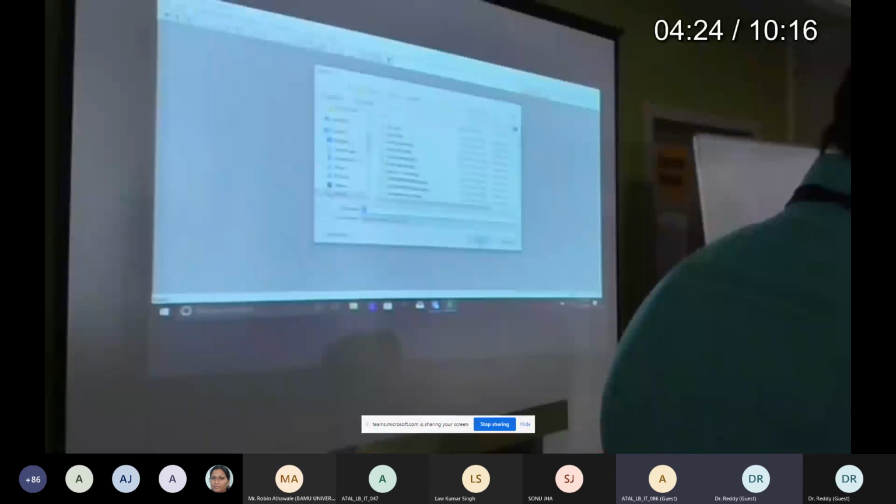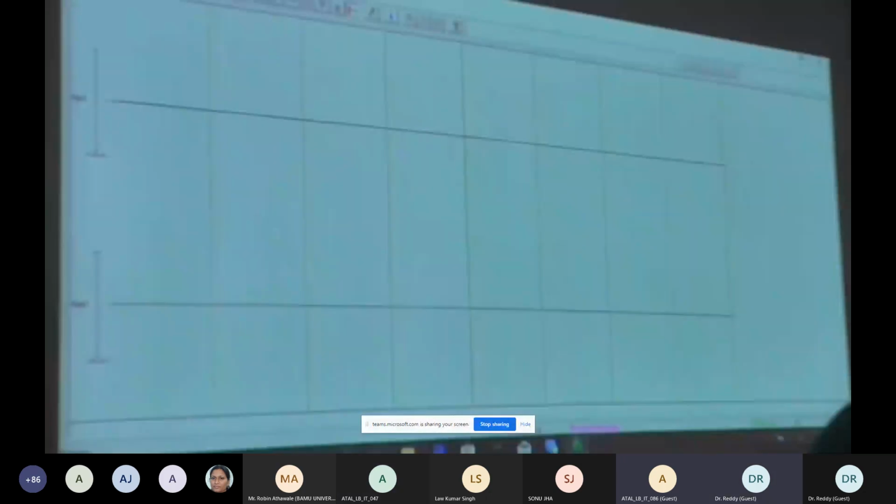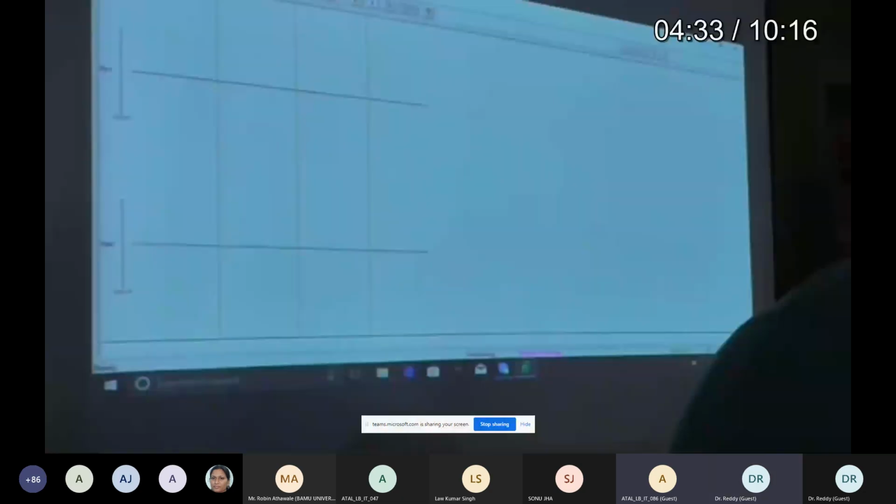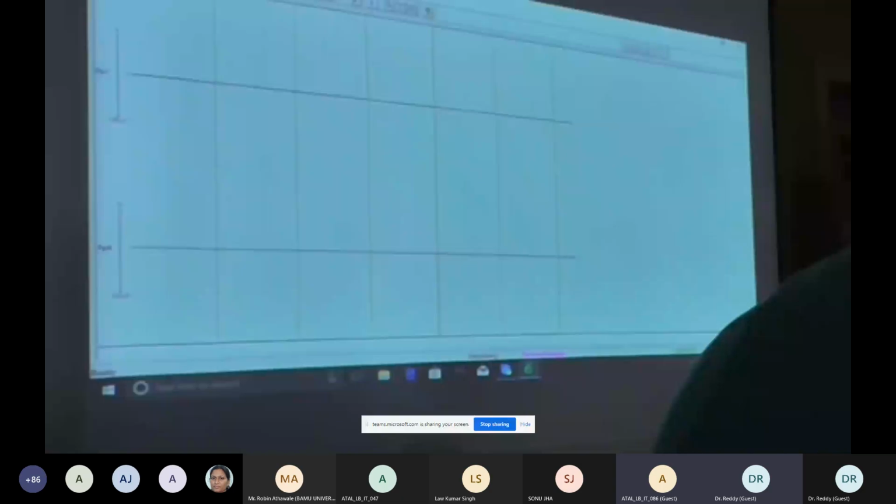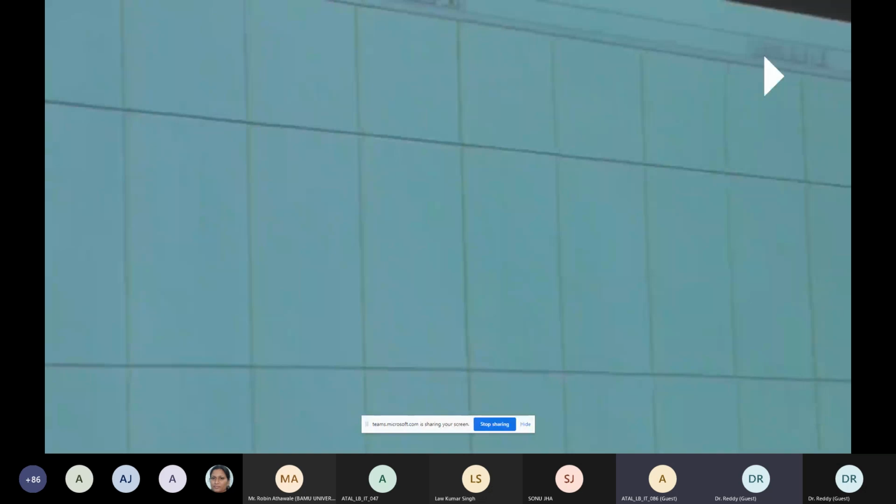If you see now, I think signals are coming 0 previously. See, one second. See the signals now, they are showing almost 0 value. Why? Because the electrodes are not at all connected to the EasyCap. Unless it reaches the brain region, you cannot catch any signal. That's why they are showing zero value. Are you following me?